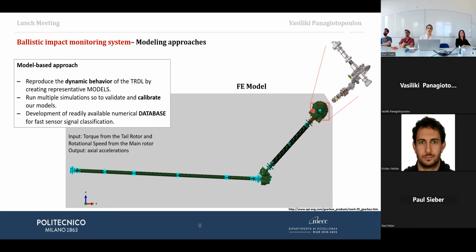And we are updating the accelerations from virtual sensors mounted on the cases of the gearboxes. The components inside this gearbox are quite complex. So a really basic post-processing of the CAD parts was performed, like removing, for example, the teeth of the gear and removing some features in order to simplify the part. But there are some questions regarding how well some other parameters have been modeled, like the boundary conditions.